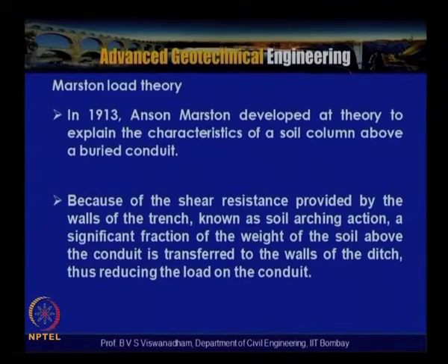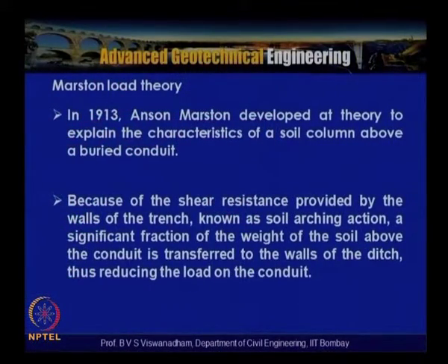Soil arching is a phenomenon in which a yielding mass transfers the forces or stresses to the non-yielding zones. Because of the shear resistance provided by the walls of the trench, known as soil arching action, a significant fraction of the weight of the soil above the conduit is transferred to the walls of the ditch, thus reducing the load on the conduit.